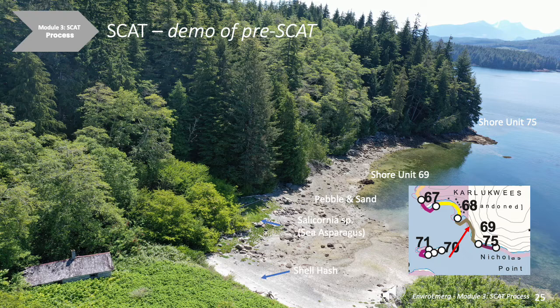Bedrock is a natural barrier to oil penetration. There can be different types of treatments throughout this shoreline unit. As such, you might want to separate this shoreline unit into 3 different units, according to treatment strategies, and different endpoints for cleanup. Breaking up a shore into more segments is advanced SCAT training.